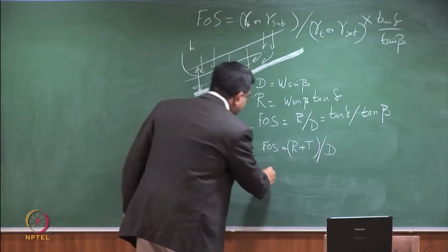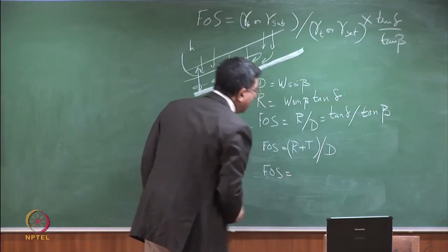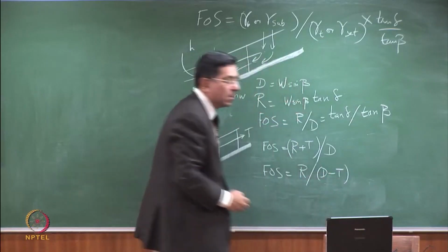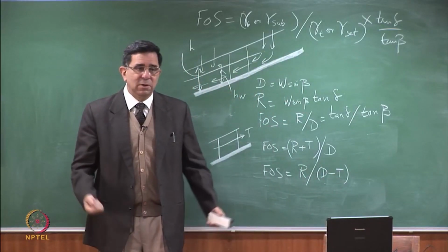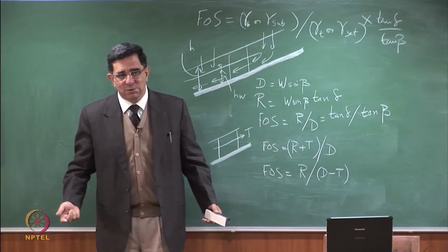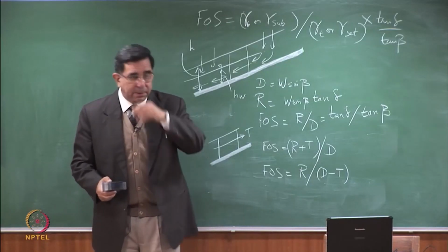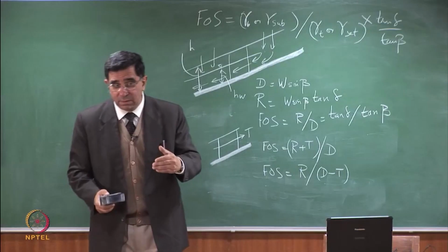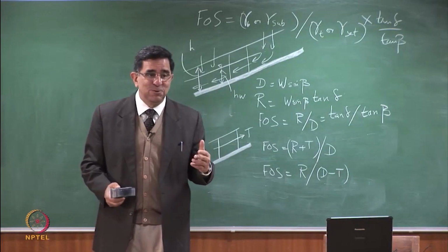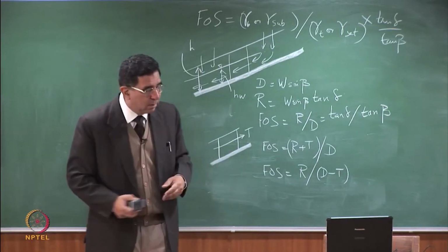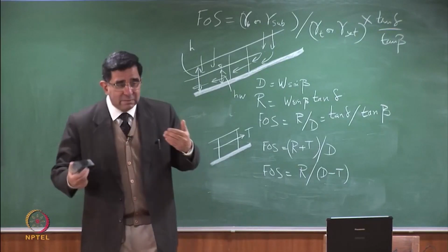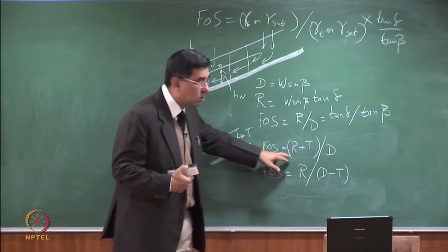The other approach is, what it says is that the tensile force has reduced my driving force. So it's the way that you define your factor of safety that's important. And unfortunately, both these formulae have been used in literature. So I'm just putting both of them on here for you. You can use either. As an individual, I prefer to use the top formula.